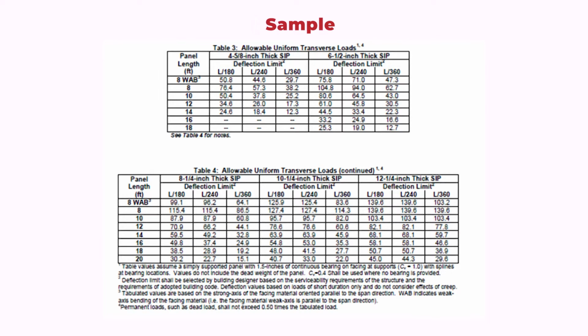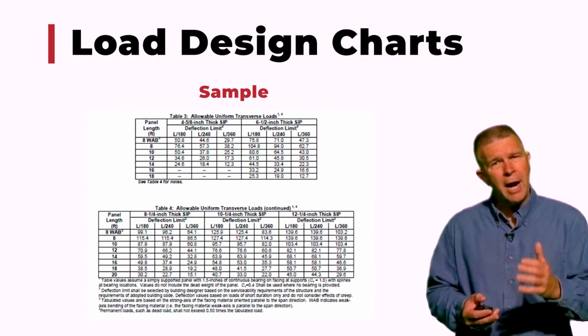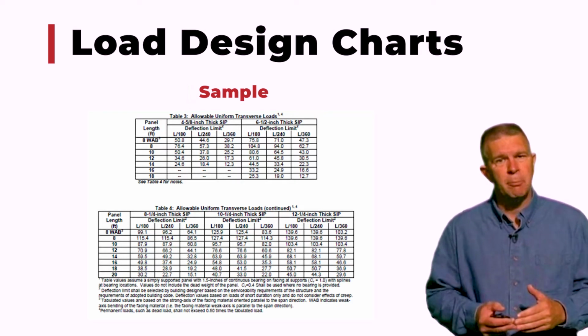It's these load design charts that give the basic information that architects, designers, and engineers utilize in making the design decisions to determine how the panels are going to be joined, the thicknesses of panels that are going to be used, and how far the panels can span. It's beneficial for you to understand that these load design charts are not only available, but how to use them, and to know when you're asking a panel to do something beyond its capabilities.